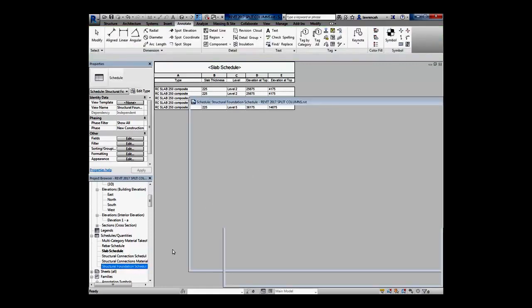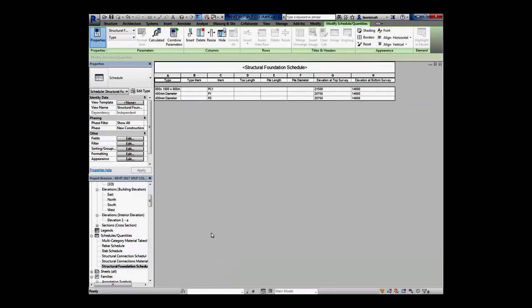In a very similar theme, we can do exactly the same for foundations. So you'll notice here that I've scheduled out a pile cap and the 2 piles inside the pile cap. So again here, I have from the survey point the top of the pile and also the toe of the pile as well, again from that survey. So some small productivity changes there, but very, very useful.